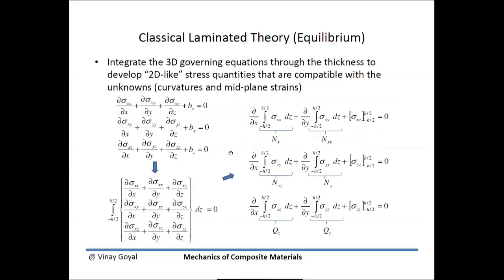So here's what we're going to do. We're going to take these equations and integrate these equations through the thickness. That is what we're going to do. By integrating these equations, we'll find that these 2D-like stress quantities will be compatible with the curvatures and midplane strains that we had previously discussed. So I'll go ahead and do that.